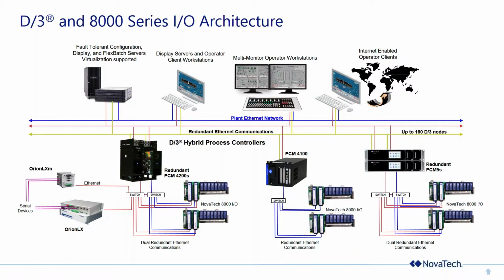If neither EBIM can communicate with PCM A, but can communicate with PCM B, then the micros will switch. So again, we minimize the impact first by just switching cables, essentially, then by switching EBIMs, and finally, as the last resort, switching PCMs. And this arrangement can survive multiple failures. You can have breaks in different segments of your Ethernet and still never lose communication because of the ability to route through those switches.